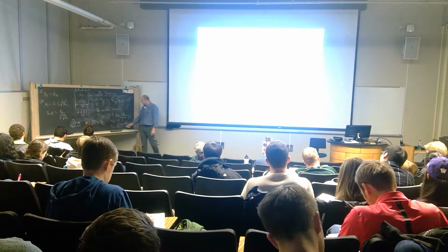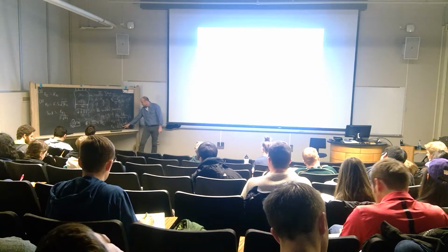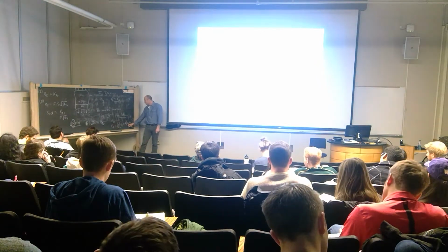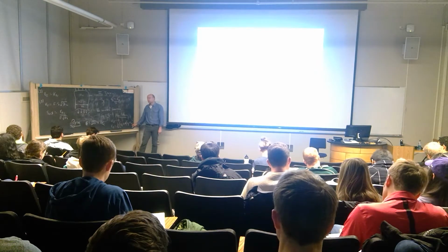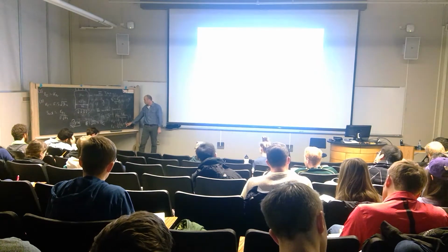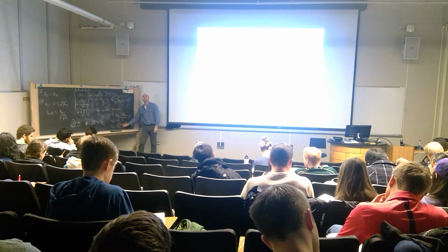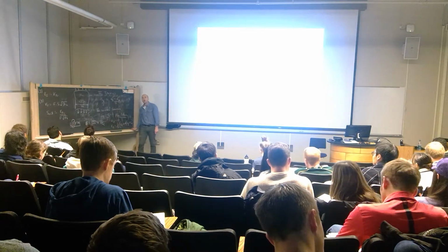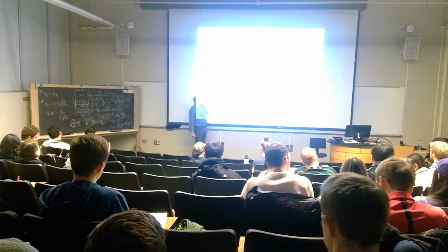So in this case we can solve for sigma z, and we find that sigma z is equal to nearly the average of sigma y and sigma x, if we think about this component just undergoing the onset of yielding, where Poisson's ratio will tend toward 0.5. So it says that sigma z is an intermediate stress. It's almost the average between sigma y and sigma x. So what does this mean to us?